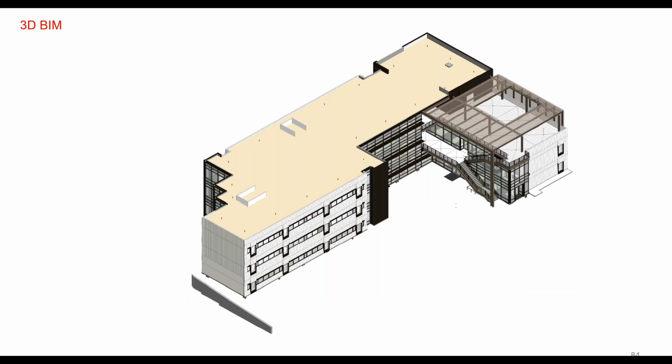So there are workflows, and somebody had asked earlier about going from one software to another, or from one purpose of a model to another. There are some software tools that do this well. I still think a lot of architectural models that are built, for a BIM model, a building information model, are likely too complicated and have too much information than what you need for a building energy model. So a lot of times you end up simplifying. I know there are workflows that work well for doing it. I'd say I haven't had a great experience in my career doing that. We generally end up rebuilding a model, even if we have a 3D.